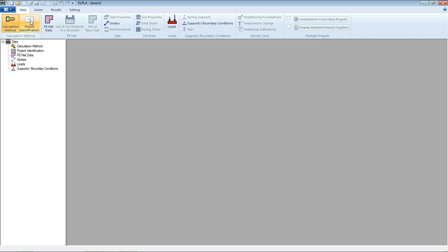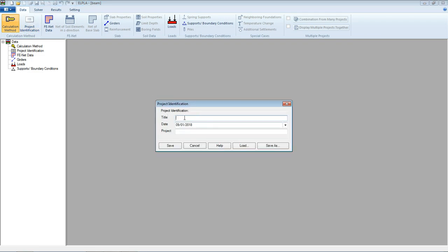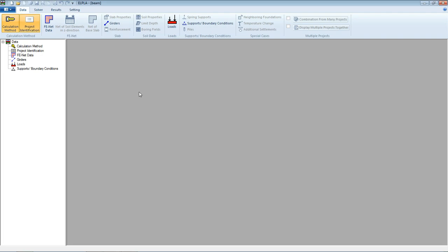Next, from project identification, we can write here the project title, project name and modify date. Project title may be analysis of beam, and project name beam, then save it.